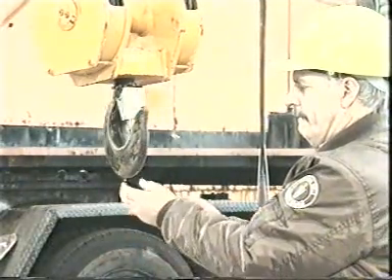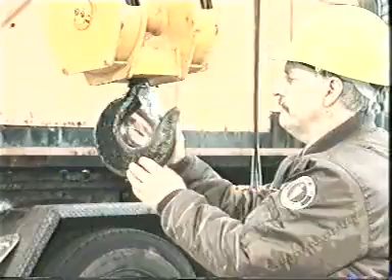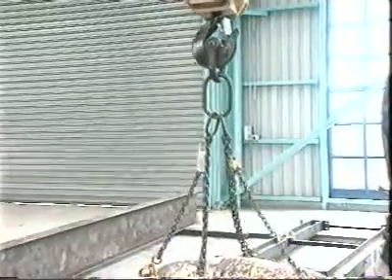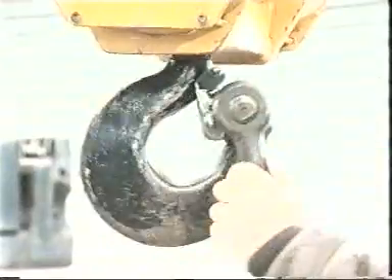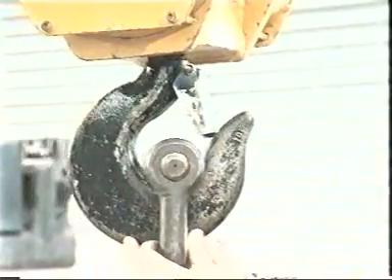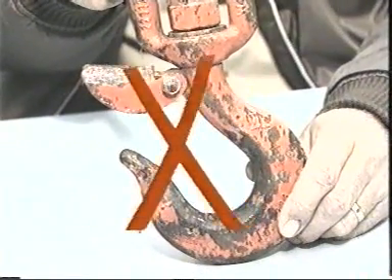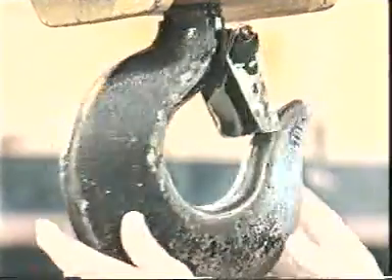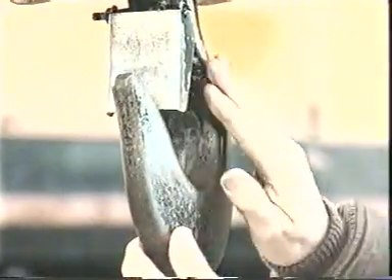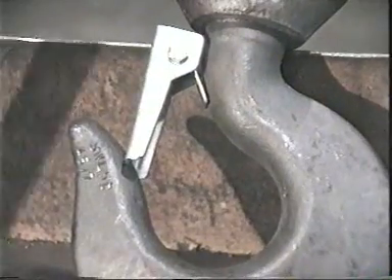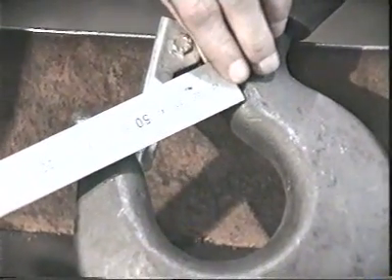To prevent displacement of the sling or load, the hook should be provided with a safety catch or other effective device to minimize the risk of the sling or load becoming detached. If the safety catch is broken or bent, then immediately have it repaired or replace the hook. Hooks should be inspected regularly for any signs of wear or damage, and the throat opening of the hook measured to see that widening of the throat has not occurred.